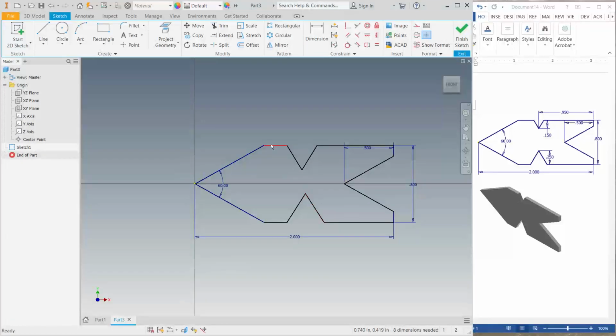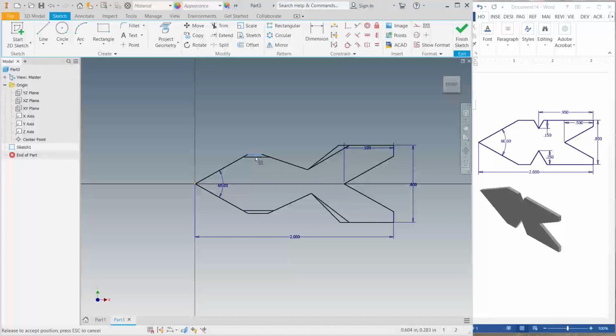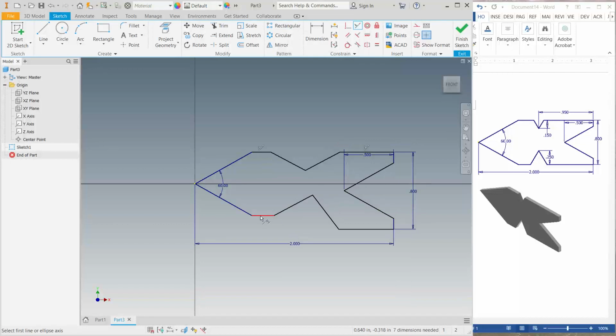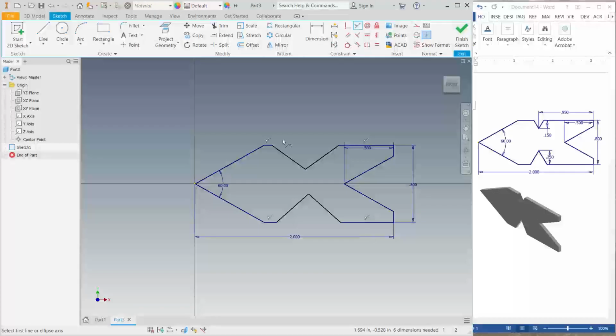Now all you have to do is to grab the lines. Just change it any way you can. So then you know something is wrong with those lines. Right now I know this line and that line are not at the same level, so I can apply the collinear constraint to make sure they are the same level. And I want to repeat that in here, so they are the same level.